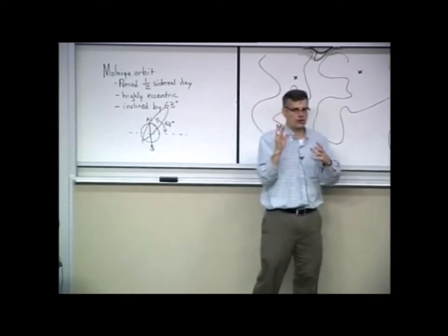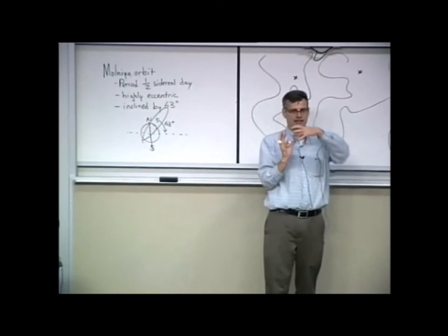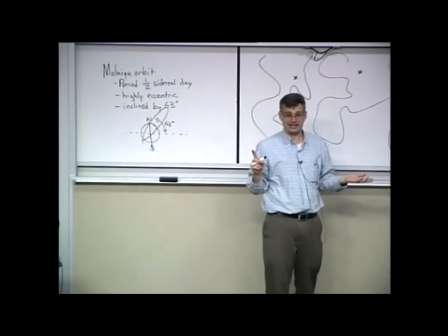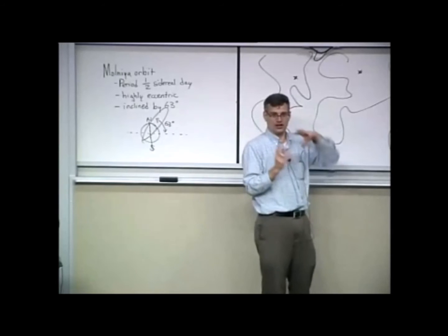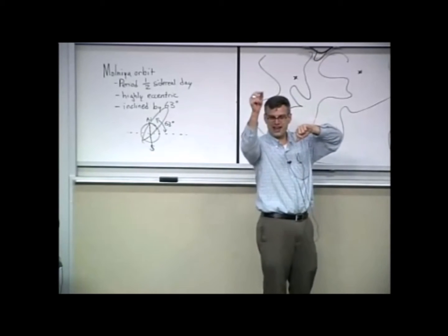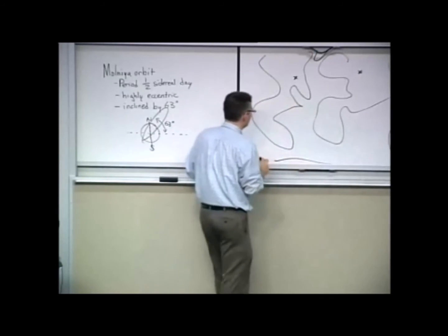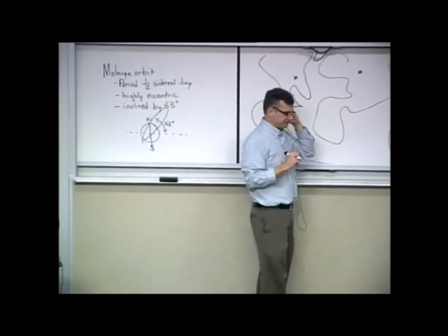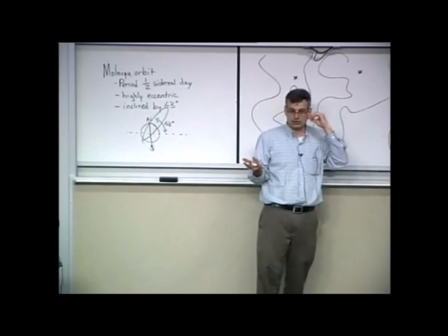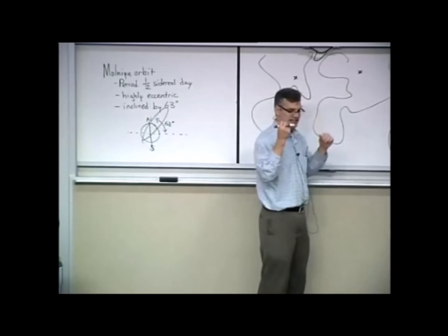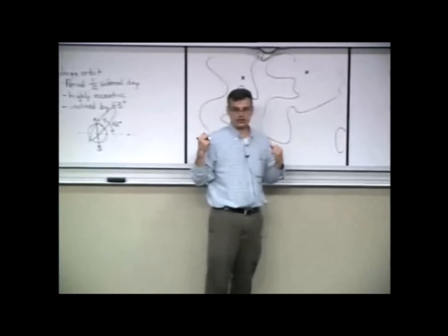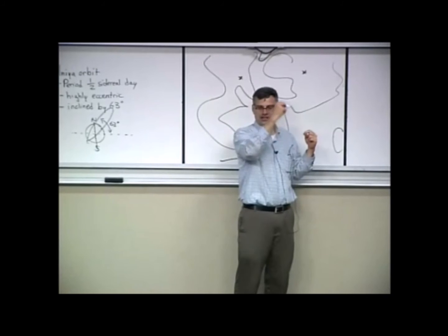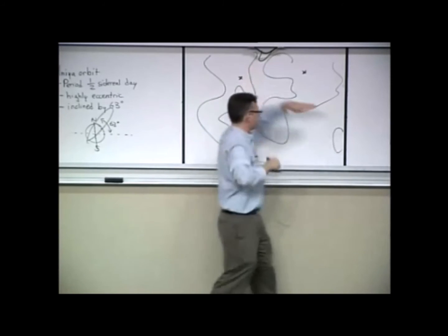Because remember, all the while these orbits are evolving, the Earth is rotating underneath them. So computing a ground track is no small task, because you've got to factor in the rotation of the Earth, subtract it out for every increment that you advance your orbital calculation. And so for the inclined Molniya orbit, we have to apply a little bit of Kepler's law, too. When it's in the southern hemisphere, at perigee, it's moving a lot faster than at apogee when it's in the northern hemisphere. So it's not going to look symmetrical here.